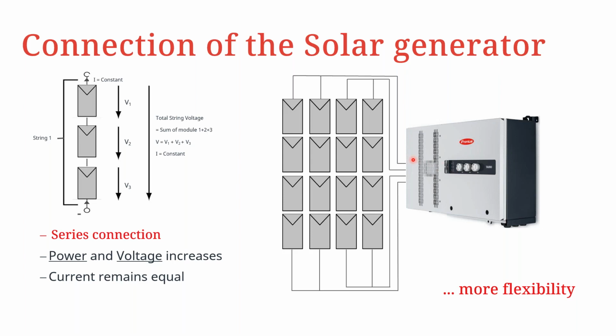So why this comes as an advantage and provides more flexibility is that if you compare it with DC-based or DC-coupled systems, the installer usually finds himself restricted in terms of module connection or orientation, because it's restricted to the control voltage of the system, which is usually the control voltage of the battery system.